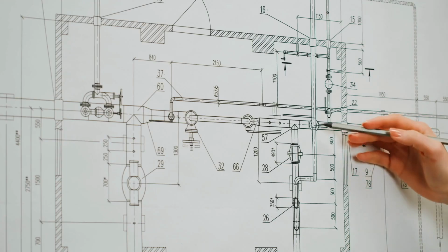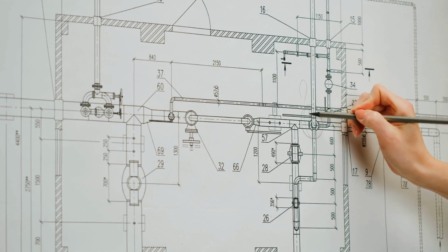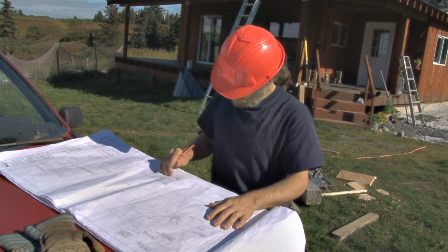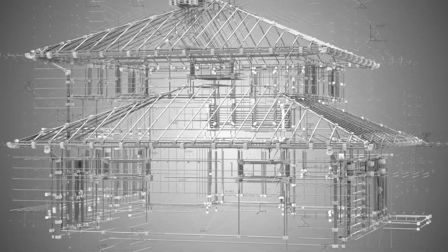The most notable of these drawing types are shop drawings. Now, shop drawings are drawn by or on behalf of contractors who will actually be doing the work. These drawings are produced with constructability in mind. For the most part, they take into account actual products to be used, as well as verified field dimensions and the actual details that will be followed to manufacture and install the work accordingly.